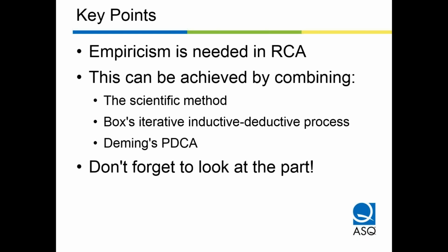Ensure your in-house people are trained and capable of performing a root cause analysis. Make sure they know how to act. And make sure you have an established, validated, functioning procedure for quality issues. Train the employees in the procedure. When that part comes back, it's a bad time to start deciding how we are going to approach the issue. There are many processes for that. I'd like to talk about it, but that's beyond the scope of today's talk.